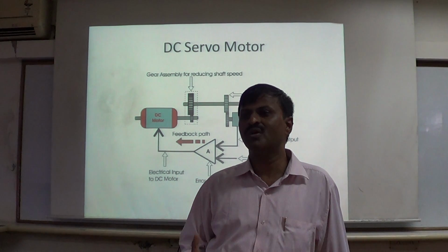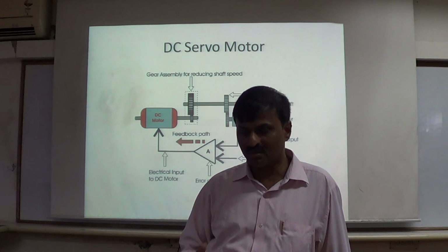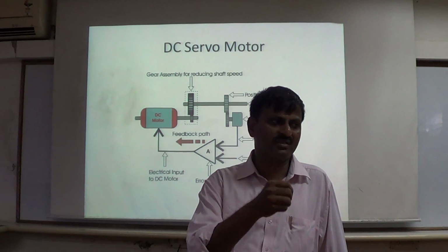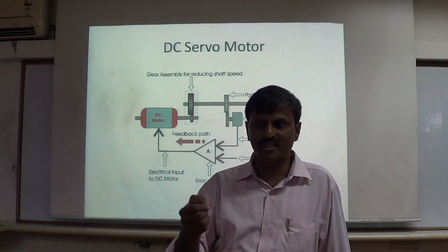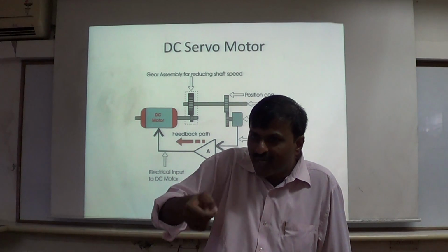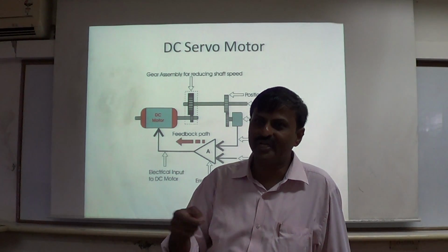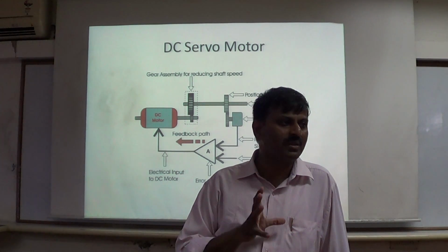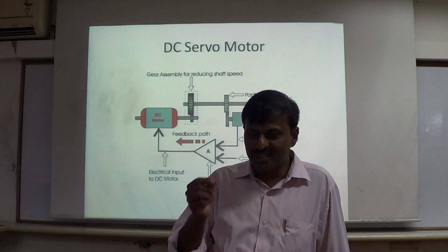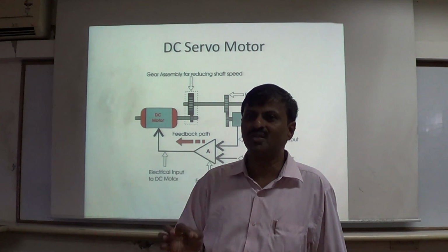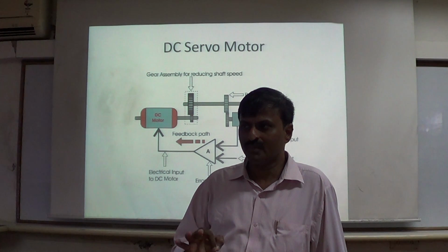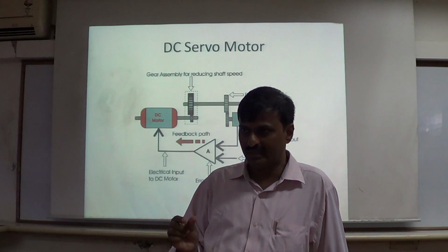use servo mechanism, not standard DC motors. Because if you want to achieve displacements in millimeters, then servo motors are best. Okay, in short, the servo motor principle is that the displacement of a servo motor is controlled by pulse width modulation, PWM. PWM signal you will have to give.